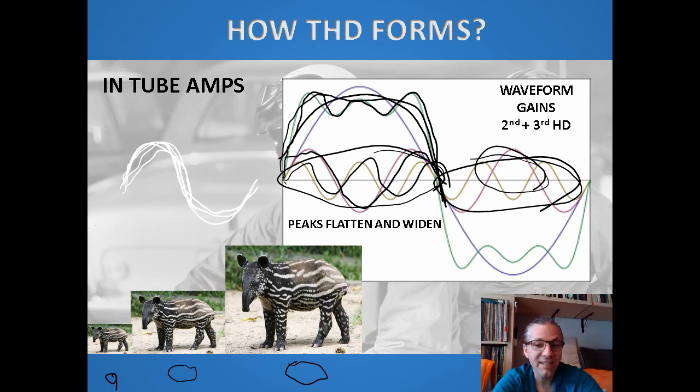And the only speaker cones that can do that relatively free cone movement in the low frequencies are high efficiency speakers, because they are high efficiency because the cone movement is not hindered by tremendous back pressure in a small tiny cabinet. So if you have an acoustic suspension speaker, it means that the cone is really restricted from movement.